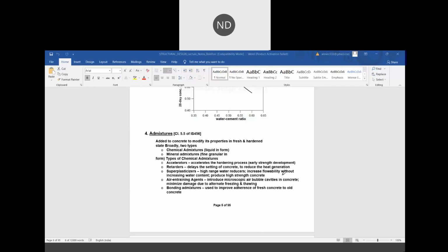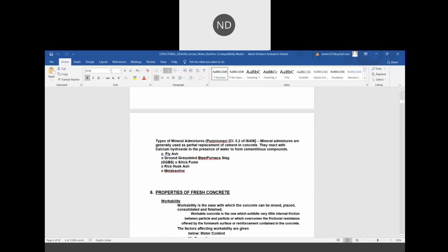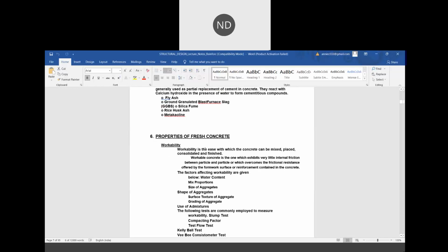We were talking about water and admixtures. Fly ash, ground granulated slag, rice husk ash and metakaolin are all different admixtures which have some pozzolanic characteristics. Like cement, they help to form cohesive characteristics, and they combine your concrete, the coarse aggregates and fine aggregates, together.